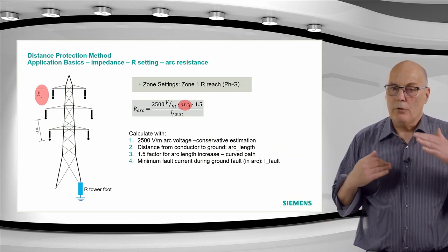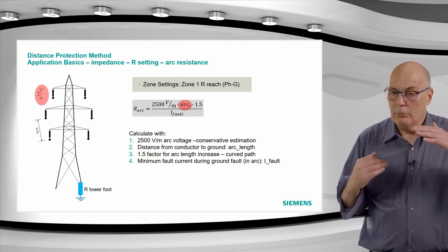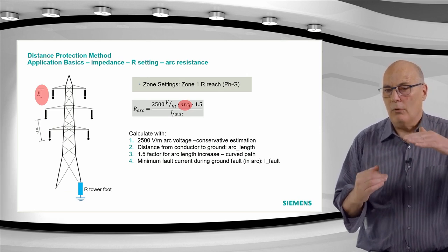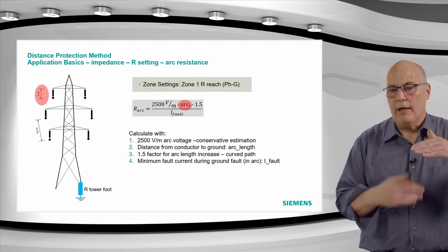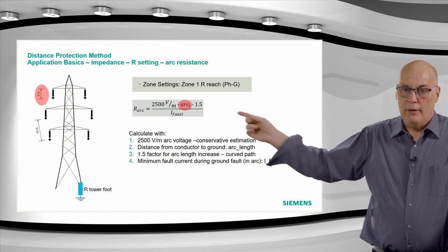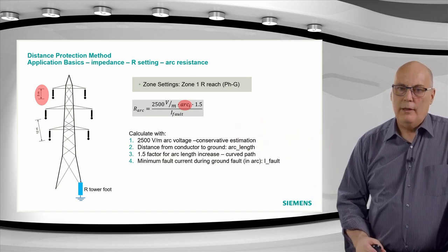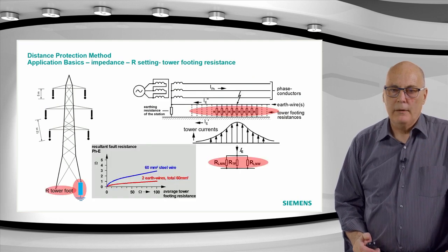Here, remember the arc voltage is a voltage, and we are simply going to measure that voltage, and that voltage and impedance, as for our relay, is just going to be that voltage divided by the current that we are measuring. So relevant here, that fault current is the local in-feed fault current to the fault.